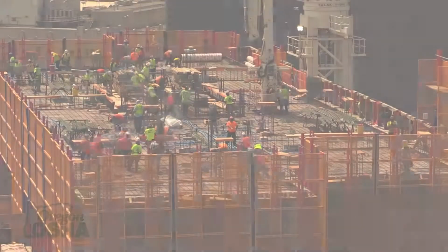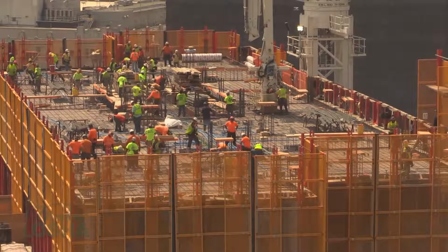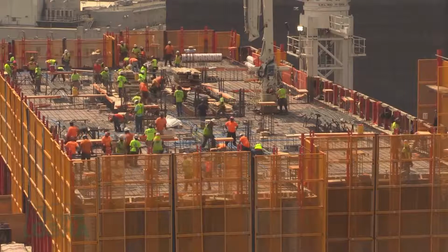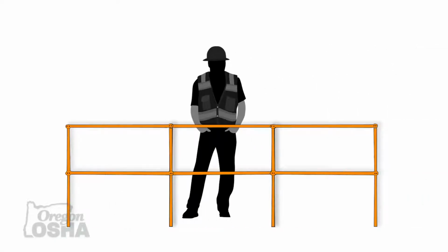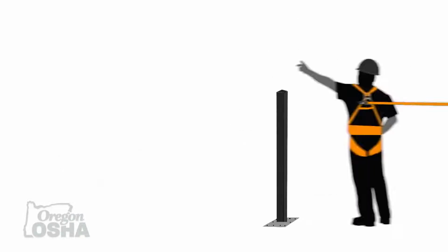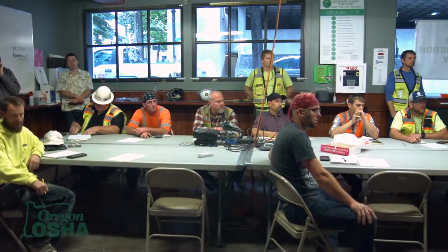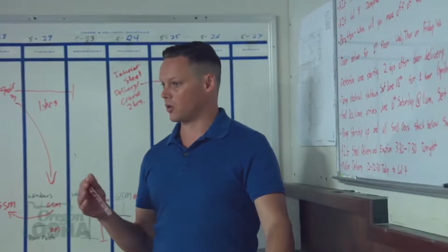The concept of preventing falls is to restrict the employee's ability to reach the fall hazard. This includes equipment options such as guardrails, hole covers, and fall restraint systems. If the first 2 strategies are not feasible, the next would be to consider controlling the worker's exposure to the fall hazard.